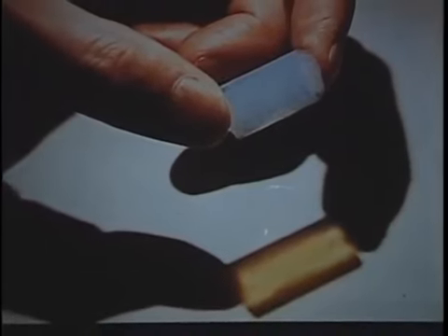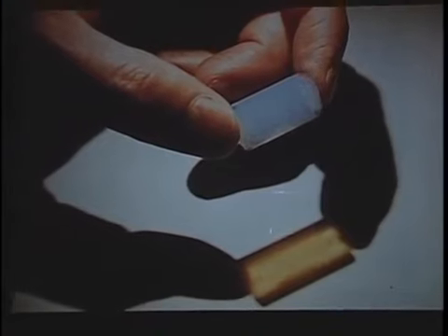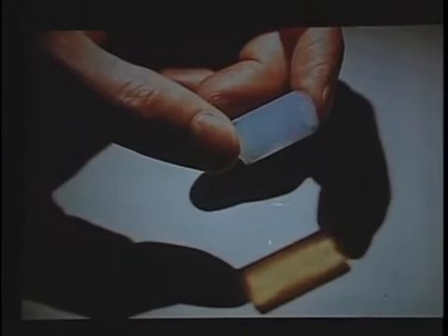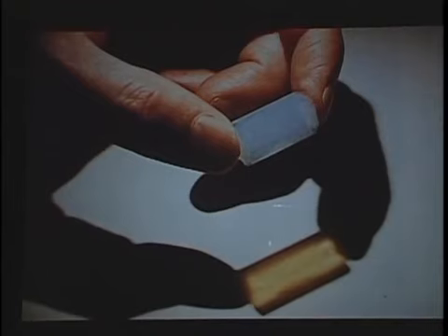The next one is a picture of a piece of aerogel. I don't know whether any of you have ever had aerogel in your hand, but aerogel has a density which is only 4 times the density of air. And it is 99.8% porous, and there are extremely small silica particles which typically have a size of only 1 to 2 nanometers. It's way smaller than the wavelengths of light.